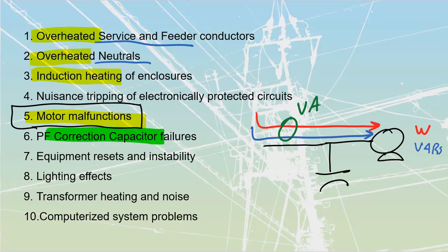What power factor correction does is we place a cap onto the system, and the cap does not remove the VARs. It is just going to take care of the VARs. So rather than us supplying the VARs from the source, we are now going to supply the VARs from the cap. The very first time we bring the cap on, there's going to be an inrush as that cap charges up. But then once we've charged that cap up, the cap and the inductive load are just going to pass the VARs back and forth between them because they're in opposite timing, in opposite directions. This is good. We like to see that back and forth action because that means that we're not taking it from my source.